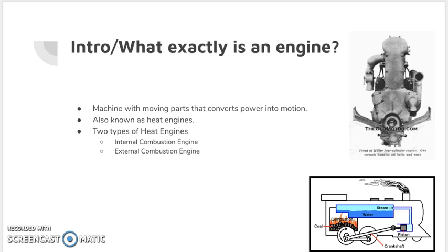The external combustion chamber is filled with a fuel and air mixture that is ignited to produce a large amount of heat. This heat is then used to heat the internal working fluid either through the engine wall or a heat exchanger. The fluid expands when heated, acting on the mechanism of the engine, producing motion and usable work. A steam engine is an example of an external combustion engine.